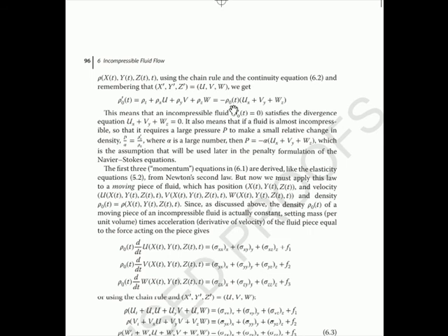And if you use that equation, divide this by rho 0, that means that pressure over alpha is equal to minus this, so the pressure is equal to alpha times that. Now that's an important equation where alpha is a large number. So you see if alpha is large, that means it's almost incompressible. Ux plus Vy plus Wz is almost zero. A small change in the volume is going to make a large change in pressure, or a large change in pressure makes a small change in volume.